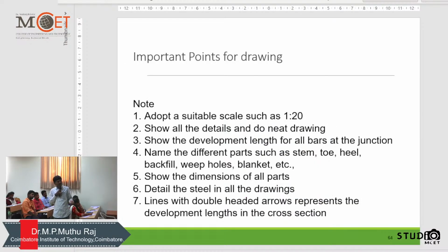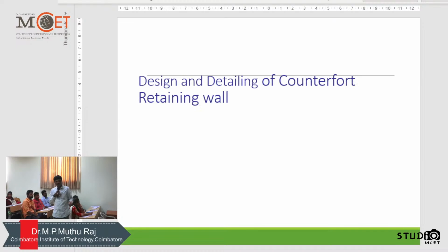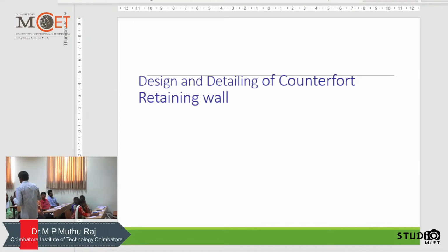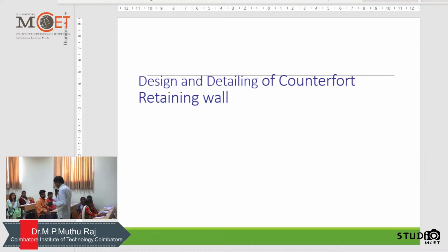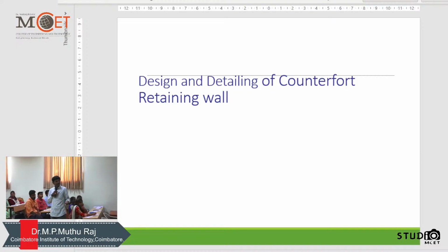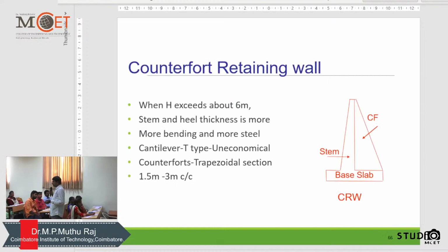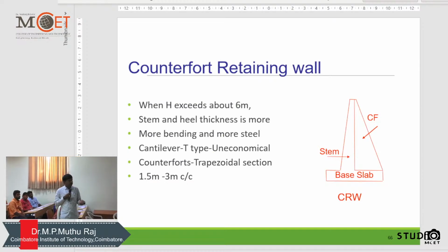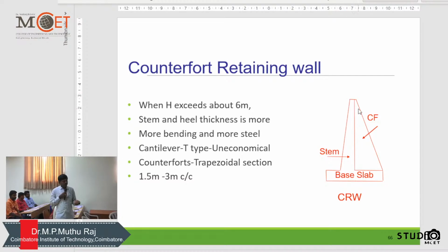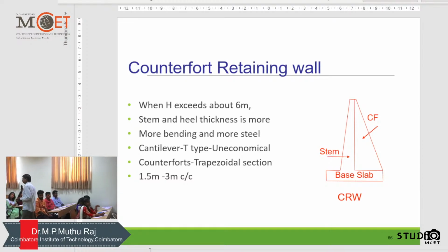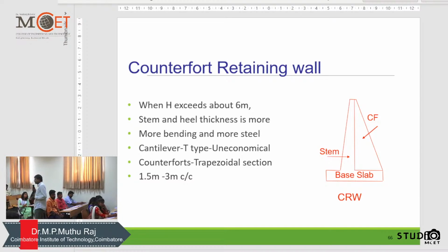So these are all the important points. And I'll just tell you the usefulness of the counterfort. Then we'll go for soil engineering. So here, these counterforts, this is a counterfort. This counterfort will be designed as a beam. Counterfort is always a continuous beam.